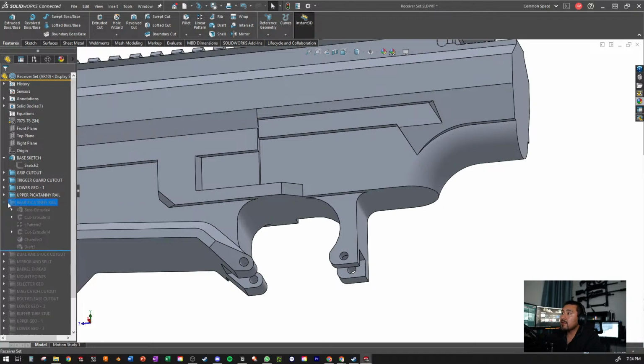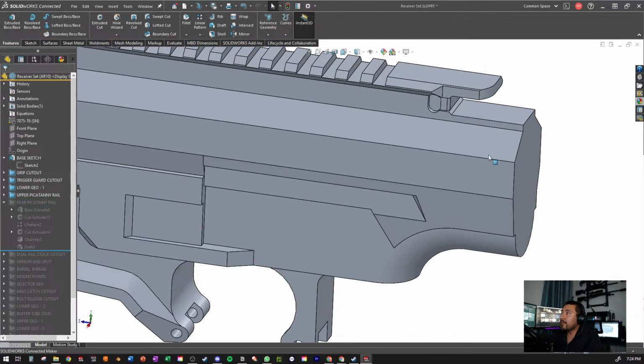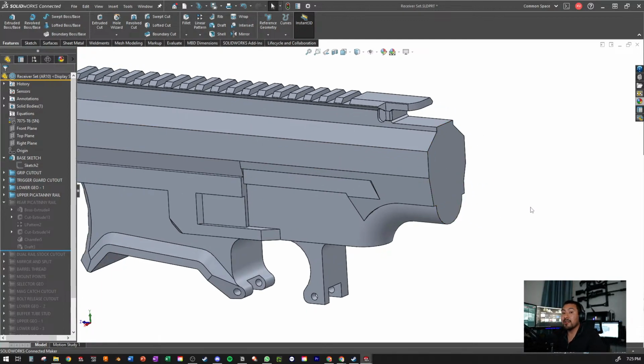And here's one of those things. Now this is that rear Picatinny. This is one of those sub-objective wants that I couldn't quite get to work properly. And here's the reason. In your product design, it helps when you have feature milestones, because it will help not destroy your tree. You don't want to destroy your tree. You can suppress it easily if you don't need it. If you suppress it, it's gone, but it's not completely gone.